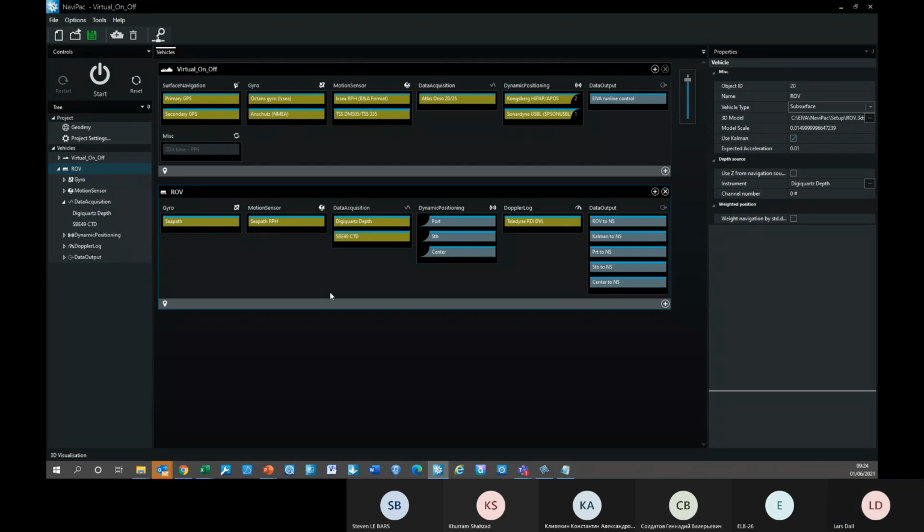That's something you have to accept, I'm afraid. But anyway, this is an important setting, actually. If you have a DigiQuartz depth or any pressure sensor that you're using as what we call a Bathy sensor, then that should be actually used. You should overrule the default setting, which is the USBL height or depth value set from navigation.